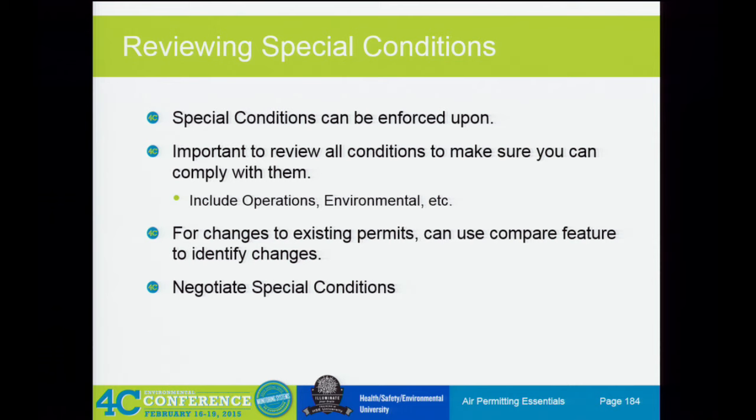So if you have more than one permit at a site, some sites will chop up their site into multiple NSR permits. Compare it against your other NSR permits and see what is going to be different about this NSR permit than your others, to see if there are consistency issues. Look specifically at monitoring and record keeping. Sometimes those can be overly onerous, and other times you'll already be exceeding them by some other requirement, and you can maybe get something taken out that's not necessary. So just pay special attention to your permit conditions, and make sure that there's something that you can live with.